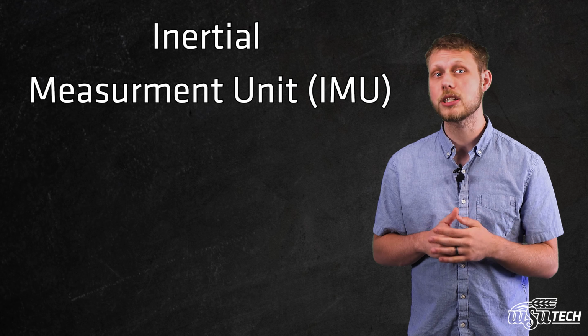Before launch, calibrate your system. That includes the LiDAR unit itself and the onboard Inertial Measurement Unit, or IMU. The IMU tracks movement and orientation and helps match the point cloud to your flight path. Without a clean calibration, your entire dataset can drift or warp.